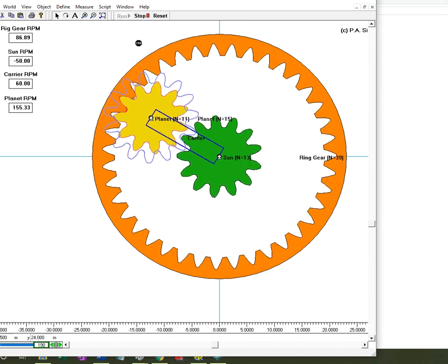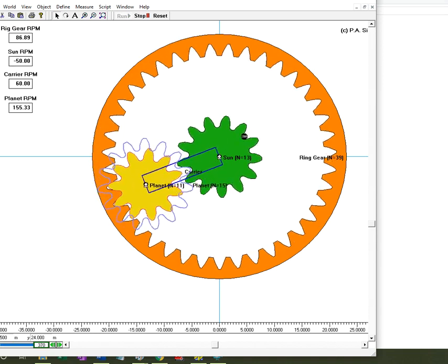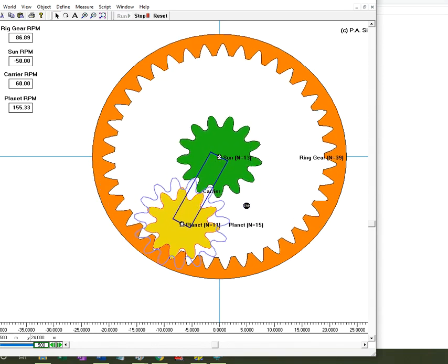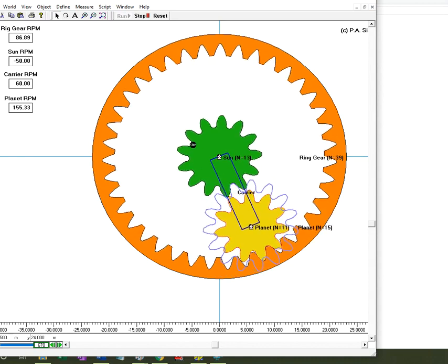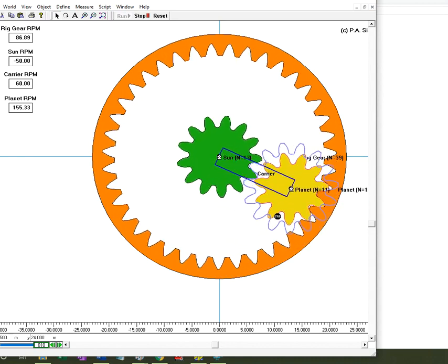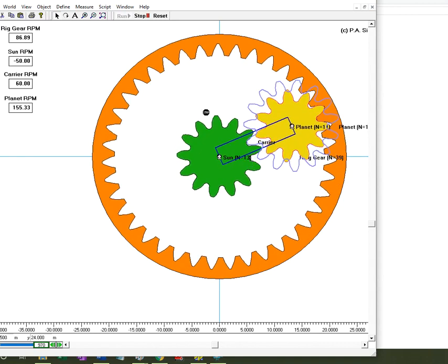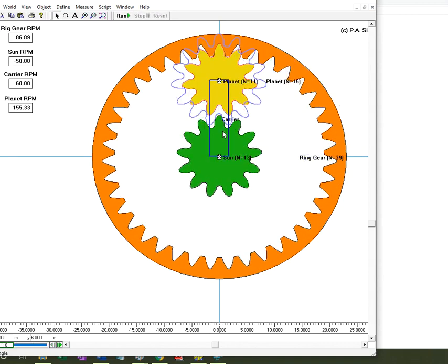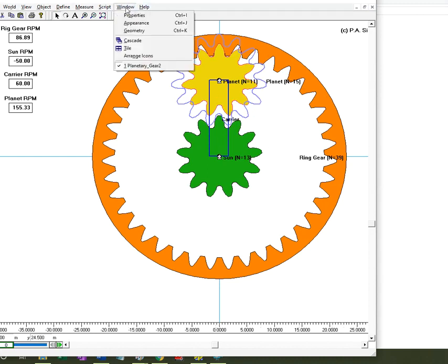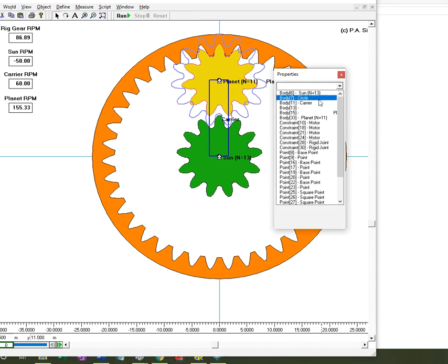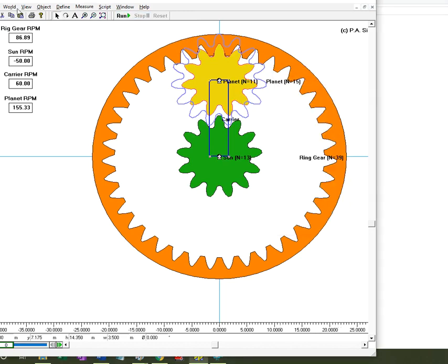And I open this up to where I can explain what motion inversion is. So we cannot write equations between the RPMs of the gears and the carrier and the number of teeth like right now. But if we turn it into a fixed axle transmission, and we can do it in Working Model by first selecting the carrier. Okay, so I have the carrier selected, and then I go to View, New Reference Frame on the carrier. See this option in Working Model, and now you're like riding on top of the carrier.